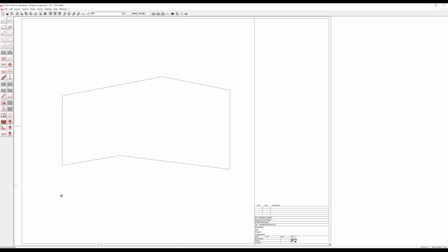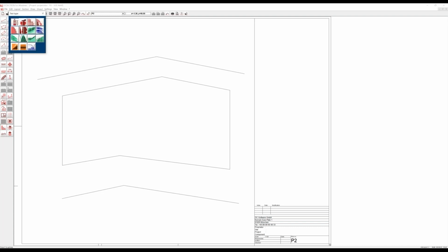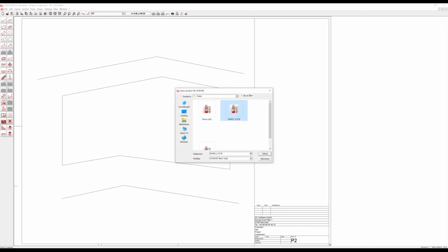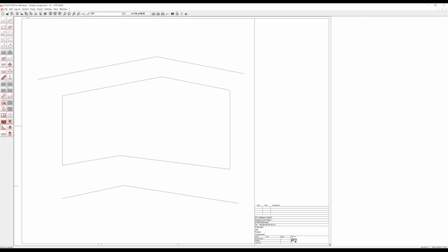We can draw streets, for example, and so on. And now we can again define where our bore profiles are located. So the type bore profile, select project file, select the first borehole log. This should be located at this position.